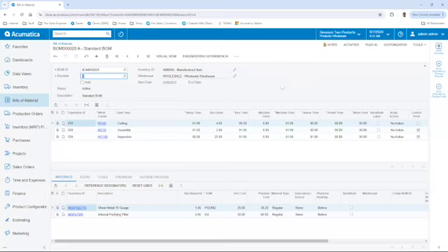All right. And then in the middle, we have what's traditionally known as a routing. And I highlight how the routing is embedded within the bill of material in Acumatica. So in my particular case, I'm saying my first operation, operation 10, is the WC40 work center. I'm doing some cutting. I'm going to take an hour to set it up, and then I'm going to be able to do 4 pieces in 50 minutes.